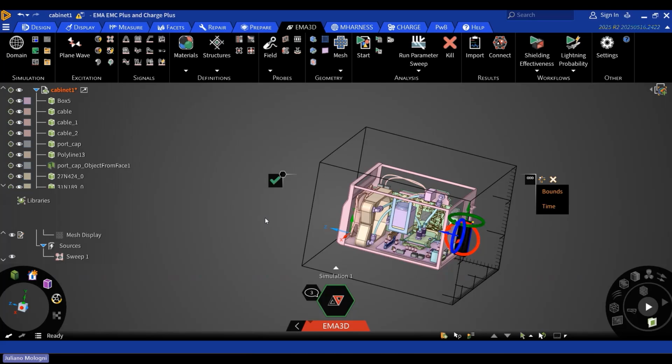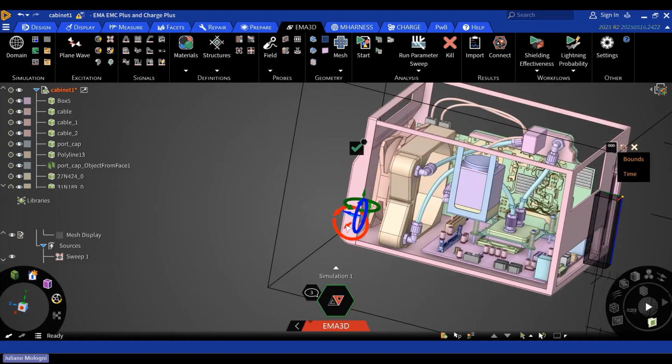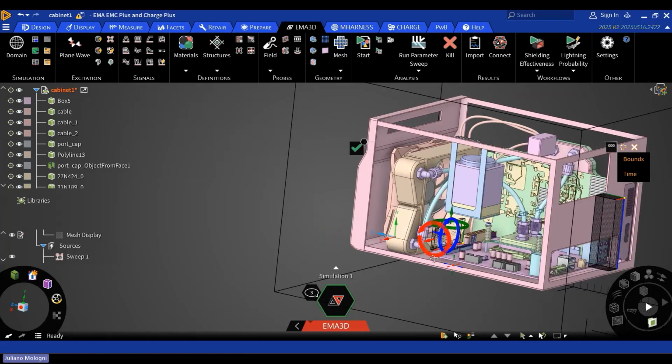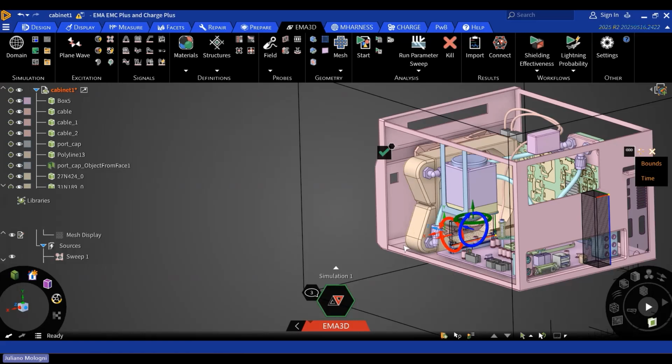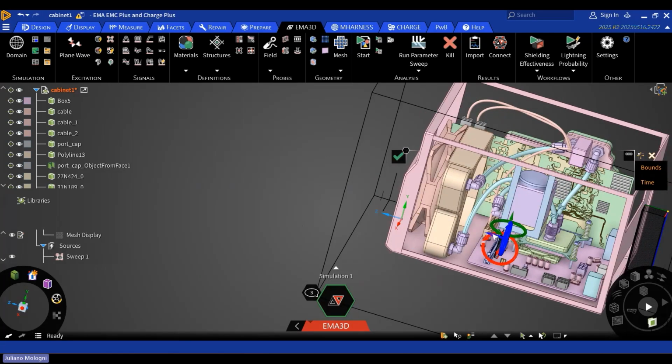So just wait a few seconds. Pretty much the same workflow. It's extremely easy. You now have the PCB from SIwave. You just drag and drop to the same place and run the EMC analysis. You can get radiated fields, induced fields and cables, compute, anything you want.